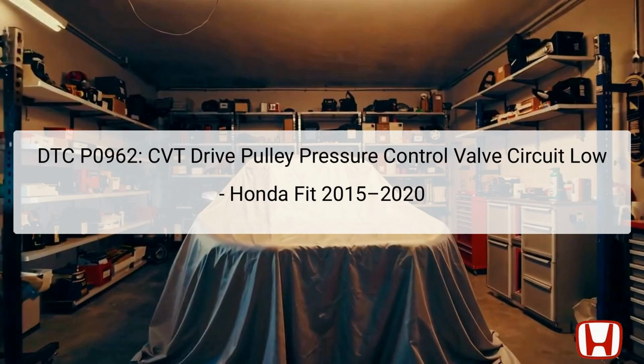The pressure control valve is a vital component of this system, controlling hydraulic pressure for efficient operation. It's relayed through the vehicle's onboard computer, known as the Powertrain Control Module, PCM. The DTC P0962 is specifically linked to electrical malfunctions and not mechanical issues within the transmission, emphasizing the need for precise electrical checks rather than assuming mechanical failure.